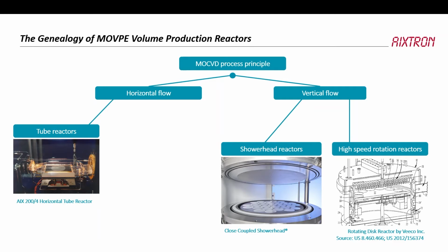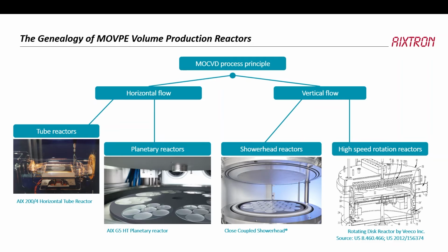Then we have horizontal flow reactors. Many of you may be familiar with these tube reactors. They were quite well known in research and development in the past, and planetary reactors. And I will talk about the planetary reactors because for, let's say, the wide bandgap materials, they are the reactor of choice for production. The vertical ones are not so interesting, I think, in that context.